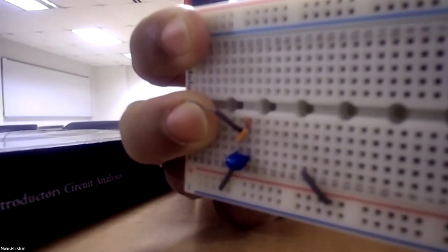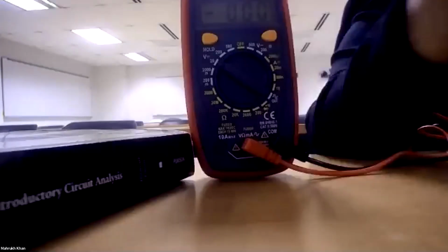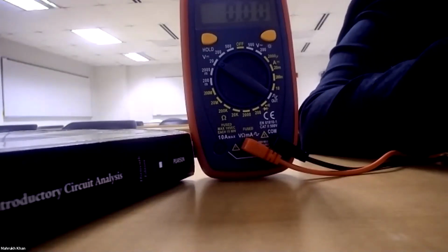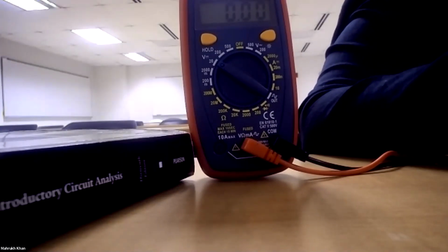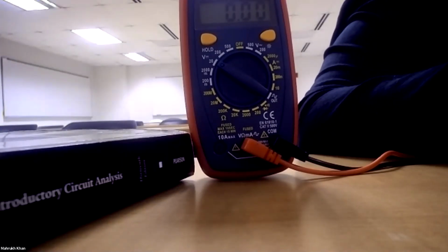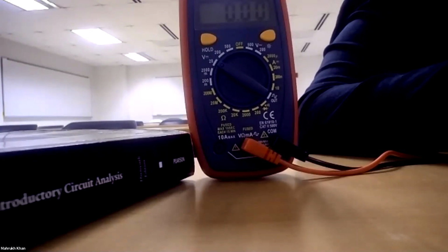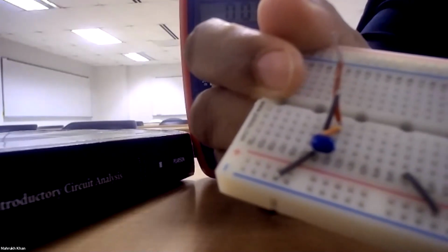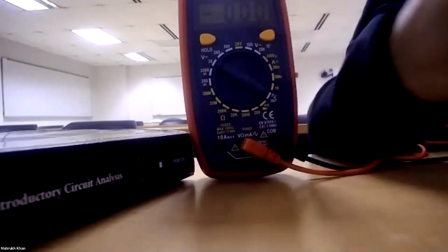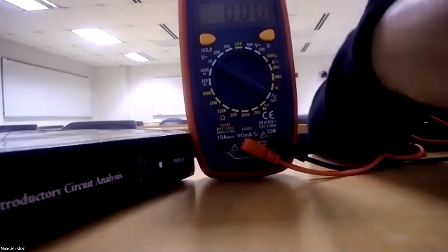Yeah. So when I have not connected anything to the capacitor, it retains its charge. And if I allowed it to discharge across the voltmeter, it was taking time. So what I did, I just shorted it with a small wire and it discharged itself quickly. Okay, is it clear?